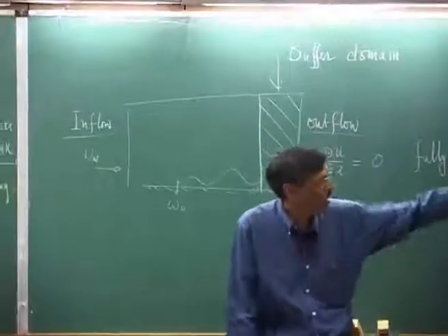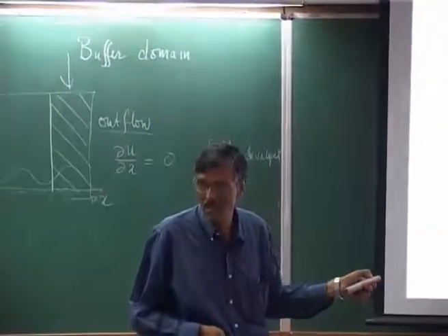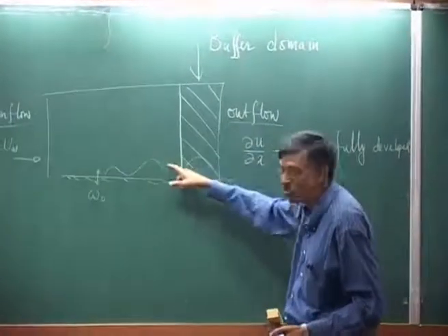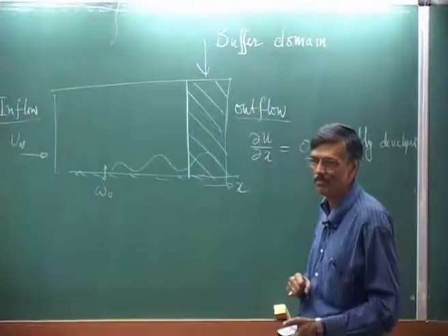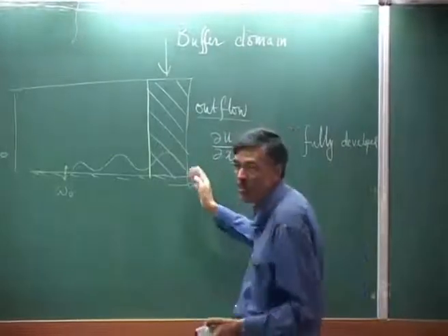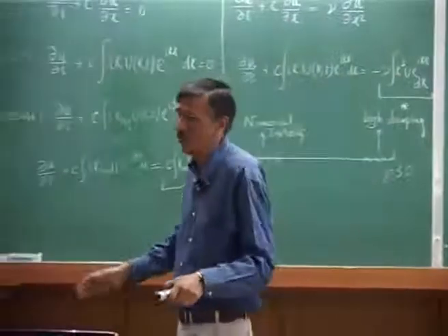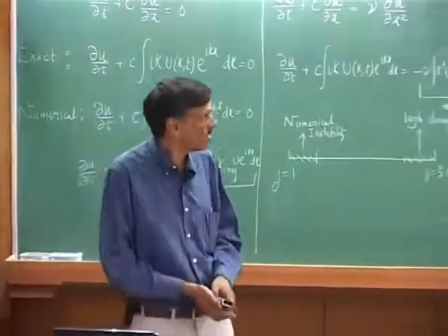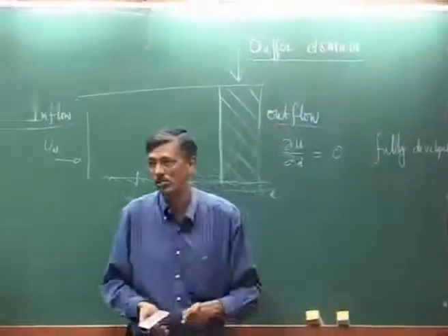With the numerical overstability like this, serious damping that we have here, instead of this wave actually growing, numerically we will attenuate it. And if we do so much that when we come to the end of the domain, the wave has artificially been damped out, there is no question of its reflection back inside the domain again. So, this is the role that a buffer domain plays in actual computations.